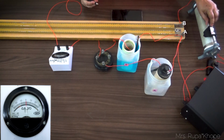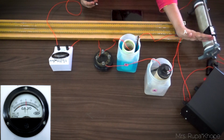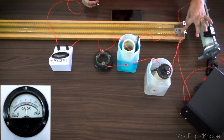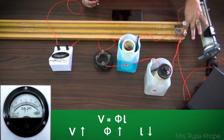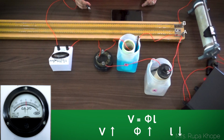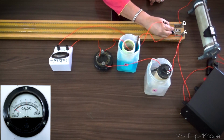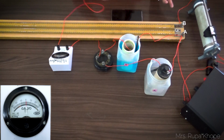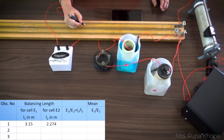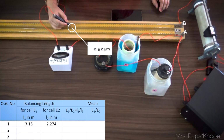For that I have slightly changed the position of the rheostat towards the fixed stat. So the voltage drop across this has increased. So now that means the potential gradient has increased. And if the potential gradient has increased, definitely we'll get the length for the less value. So let's see, put on E1, touch the jockey here, touch the jockey here. Definitely it is going to move on both sides. And then again find out the length.